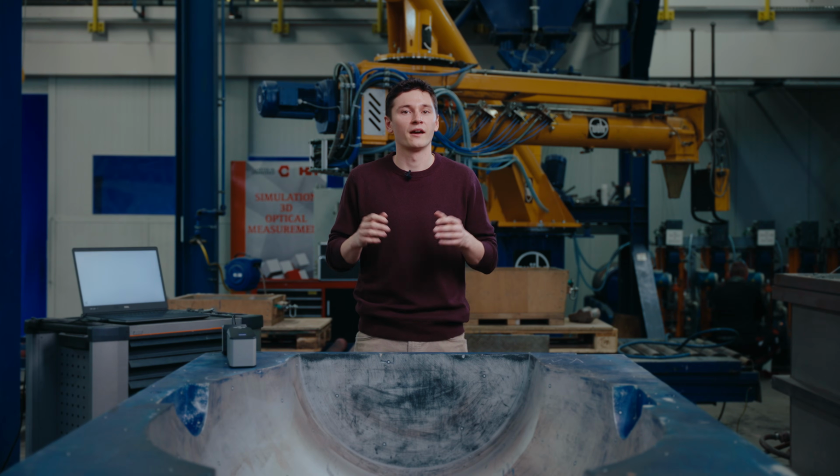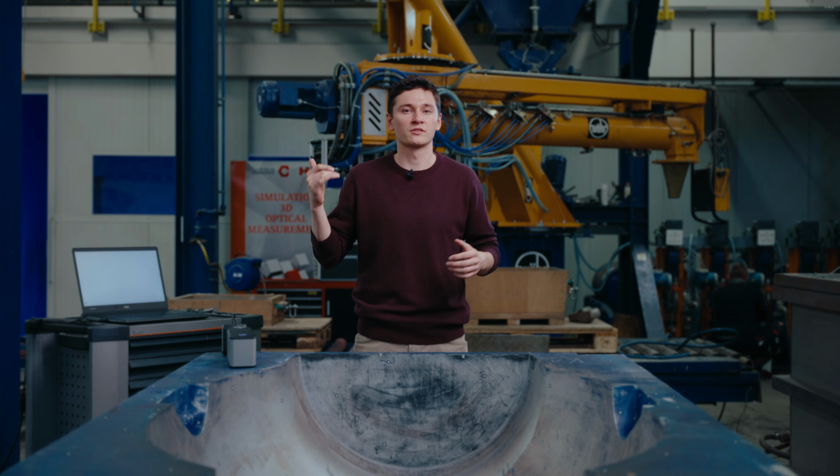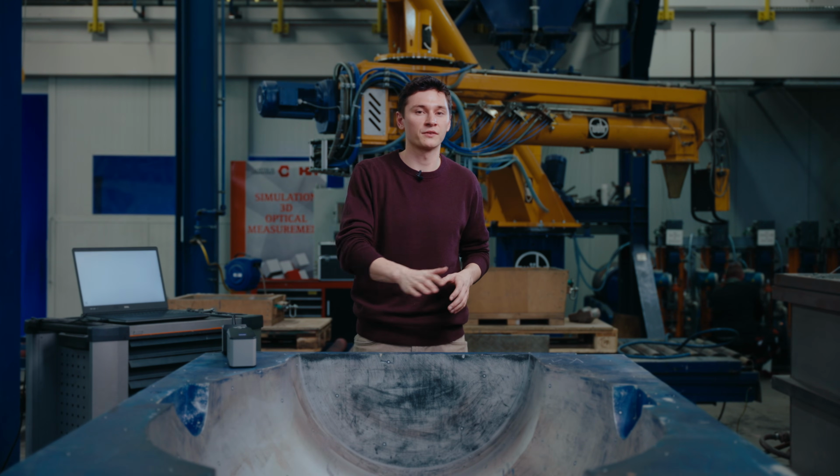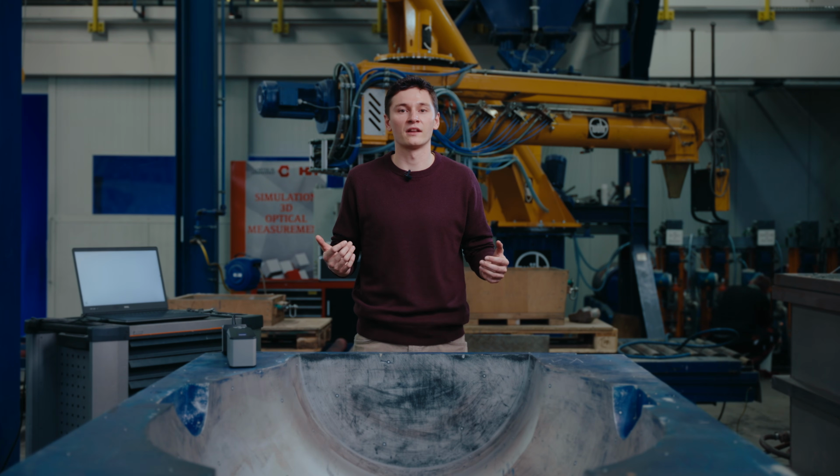If you are scanning big parts, we cannot just collect reference points by moving over the surface, as this will introduce an additional error called a stitching error. For larger parts, we would like to know the exact 3D coordinates of the reference points all around the part in order to have a stable backbone. This will be used afterwards to position the 3D scanner in space.